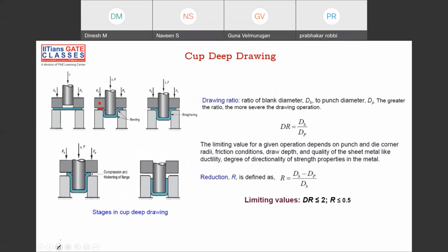That's not good. You have to apply a certain force so that some friction is exerted here, so that the sheet neither gets stuck there, nor goes too easily. It should go at a certain speed, in a certain way, not completely slipping and not completely stuck.